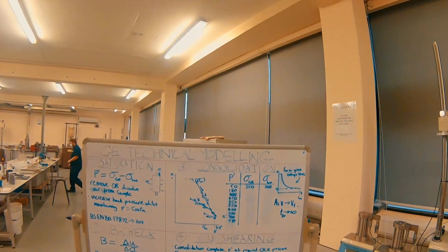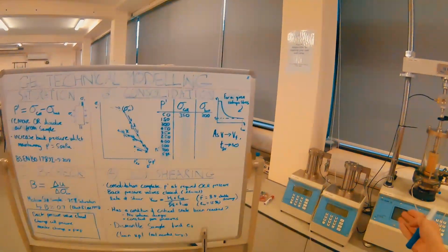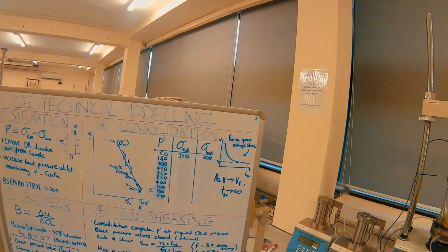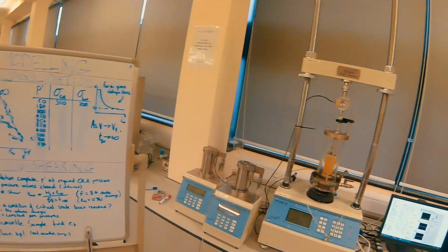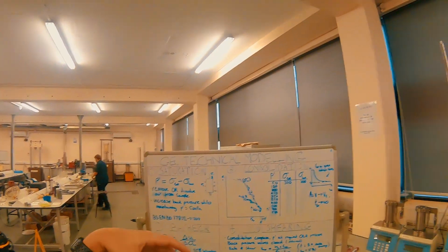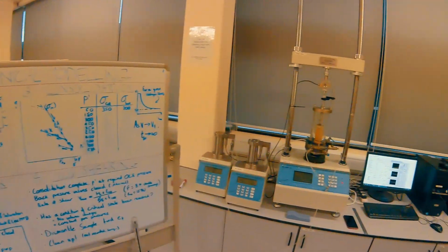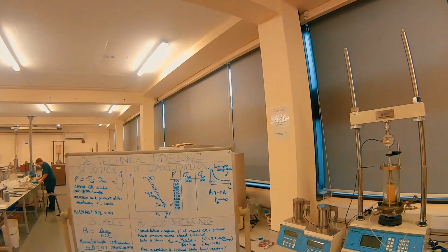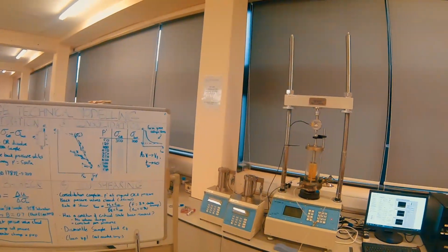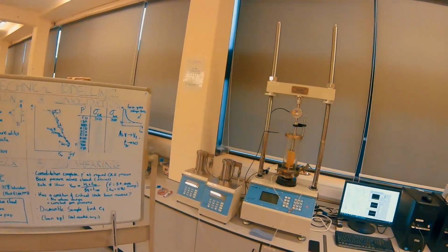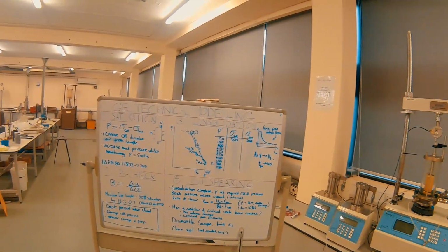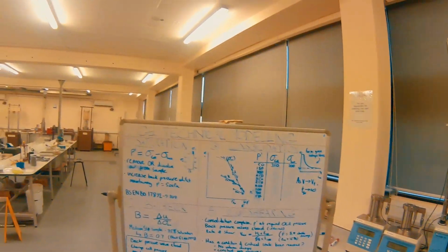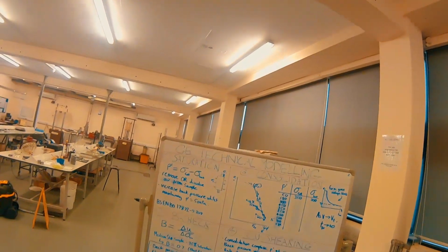How are we going to get our values of P' in our cell? One thing we need to think about is the back pressure. We'll start with that first. We've used the back pressure before when we were thinking about saturation and our B check. We closed off different valves and such. The main thing to consider here in consolidation is that you can't really decrease your back pressure. Otherwise, you will be drawing air that might be in your sample out of solution. That returns back to the stuff we talked about with saturation and flushing.